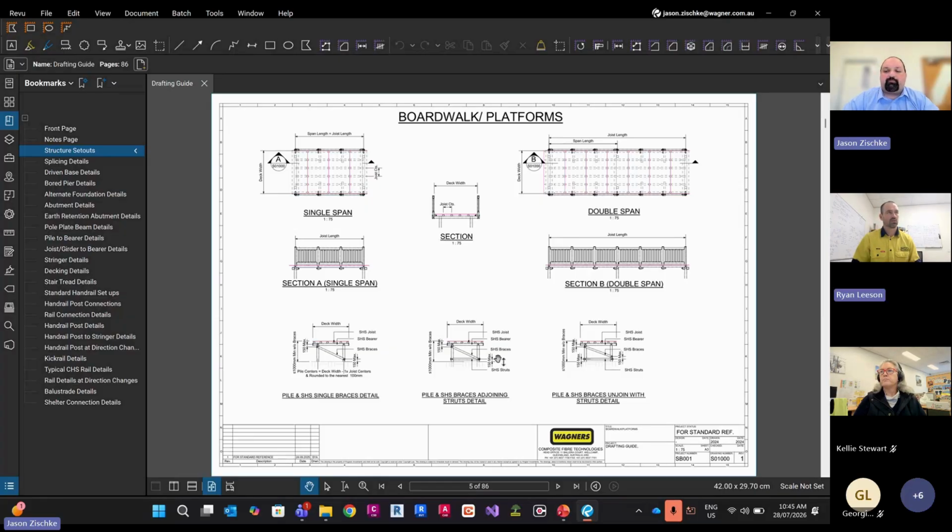Yeah, I'd say, Jace, just to add to that, if you're building with timber and you are a member short, or you need something a bit longer, it's available from the local hardware store, more likely than not. And with steel, a lot of your connection details can be made on the fly with welding, whereas with FRP, a lot more of your thinking has to be done in advance. That's probably a high-level summary that I would add.